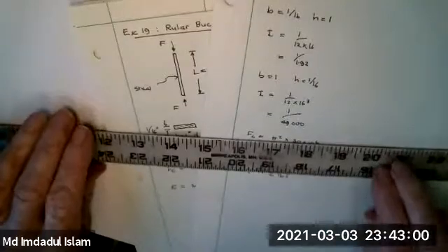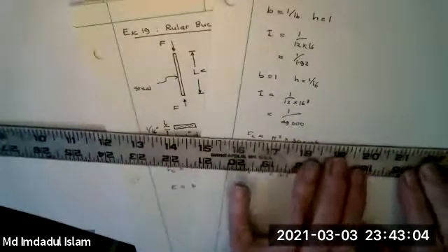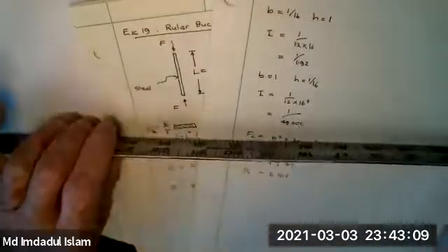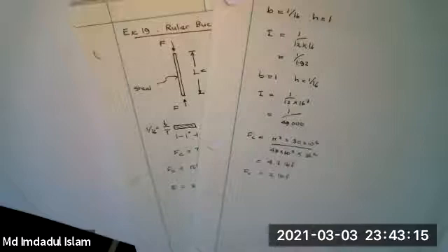Okay, you can perhaps see that it's not straight. It's got some kinks in it. I don't know how many years I had this ruler. They're not very big kinks, but they promote buckling. And so that's reality in buckling, when you think that what we do is analysis that has to be perfectly straight.